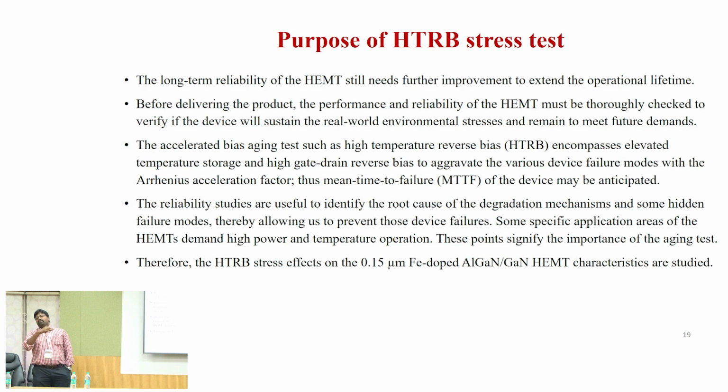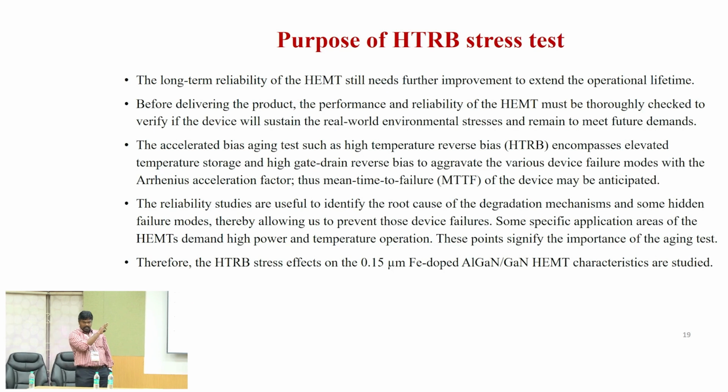Okay, so you are giving both electrical stress and thermal stress. So the advantages: you can identify the root cause of the degradation mechanism. So that's why you can understand the device failure mechanism, so you can improve the reliability of your transistors.